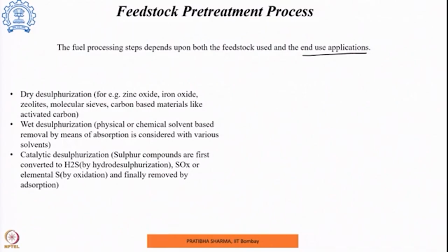Natural gas, based on its source, the composition may vary. However, the major constituent of natural gas is methane, which is more than 89 mole %. Other constituents could be ethane, propane, butane, some amount of carbon dioxide, hydrogen, and various other non-organic compounds as well. Now this desulfurization which we are looking at, hydrodesulfurization process,